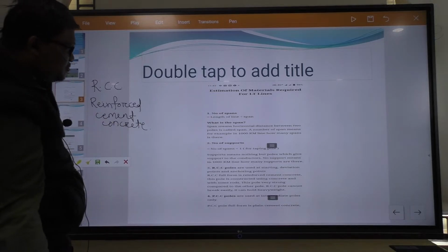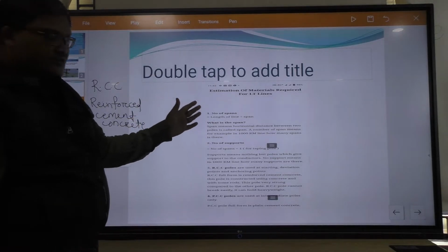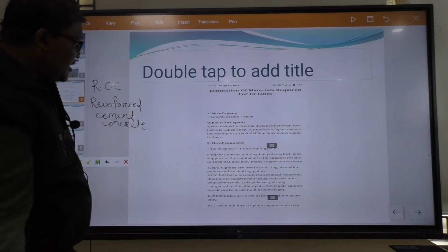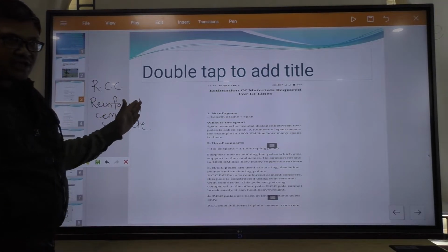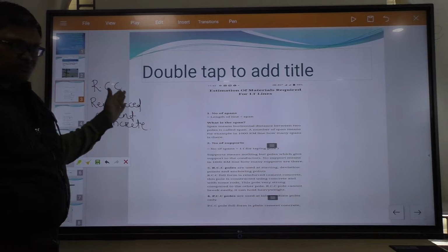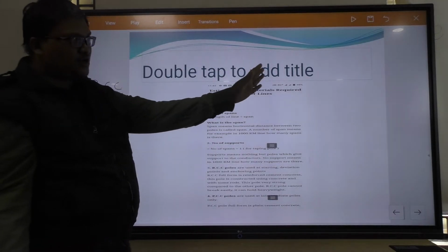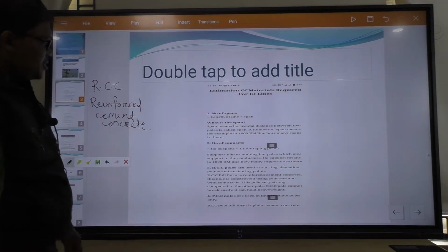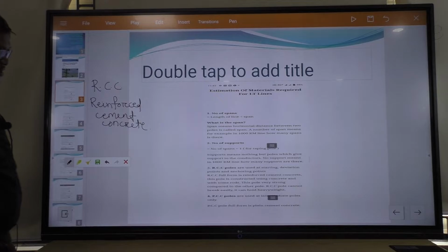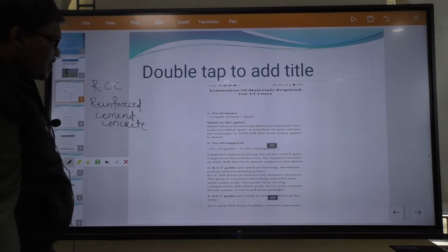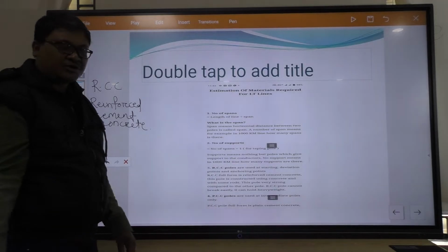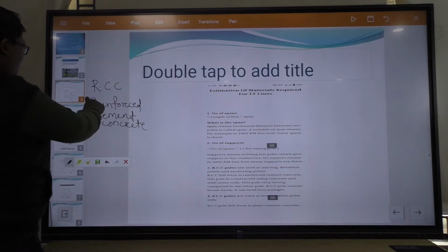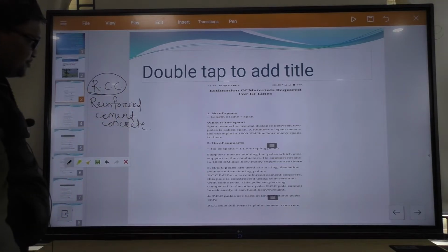That means from the start at the substation, an RCC pole is used. Anchoring points are poles along the distribution line, from the substation to the last consumer, where repair may be required. Anchoring poles and deviation points, where there is a turning point, must be RCC poles, that is, reinforced cement concrete.